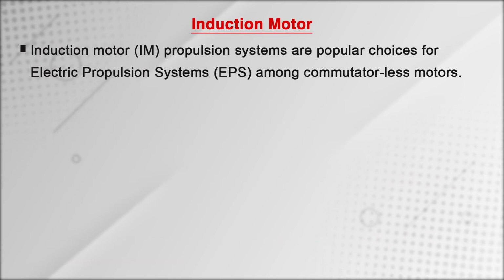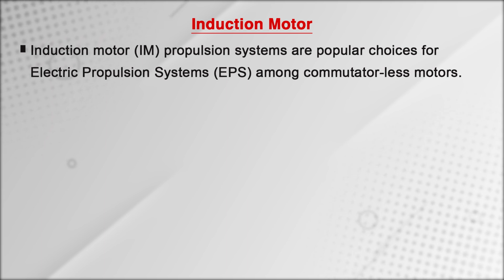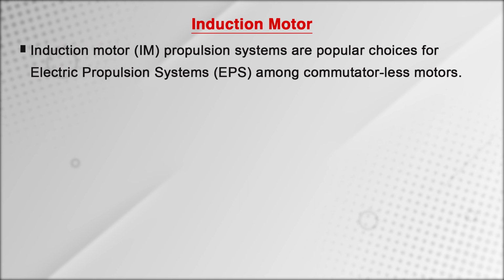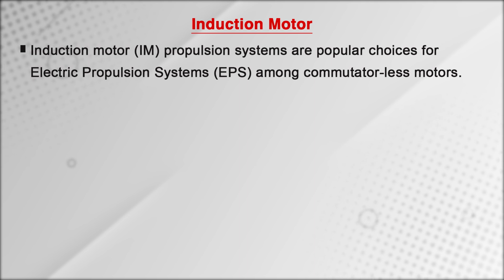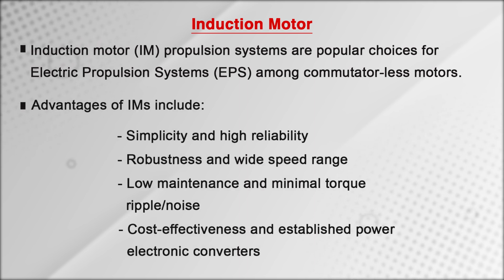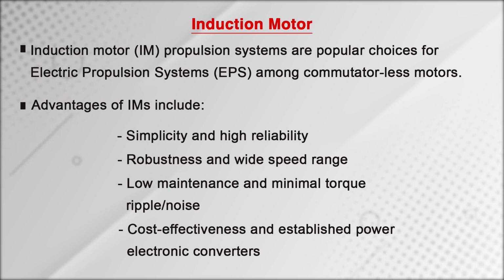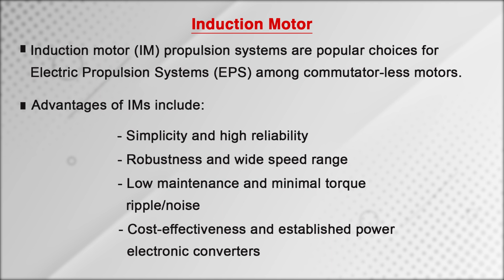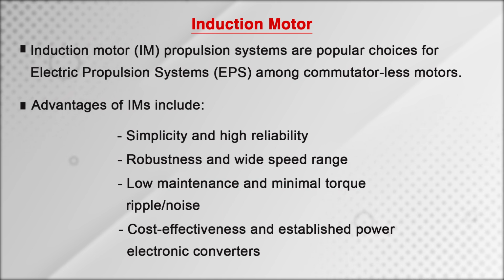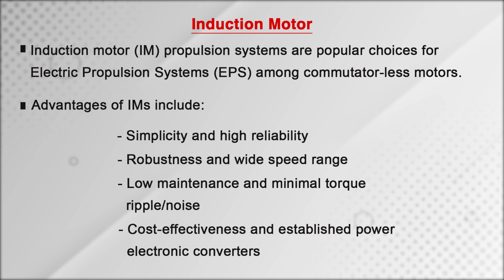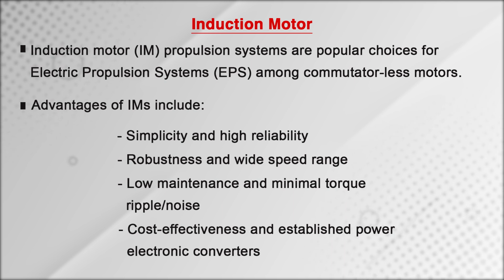Another motor technology is the induction motor. Induction motor based propulsion systems are well established and widely accepted as a leading candidate for electric propulsion systems among commutatorless motors. Induction motors offer numerous advantages including simplicity, high reliability, robustness, wide speed range, low maintenance, minimal torque ripple, less noise, cost effectiveness along with the established power electronics converters.